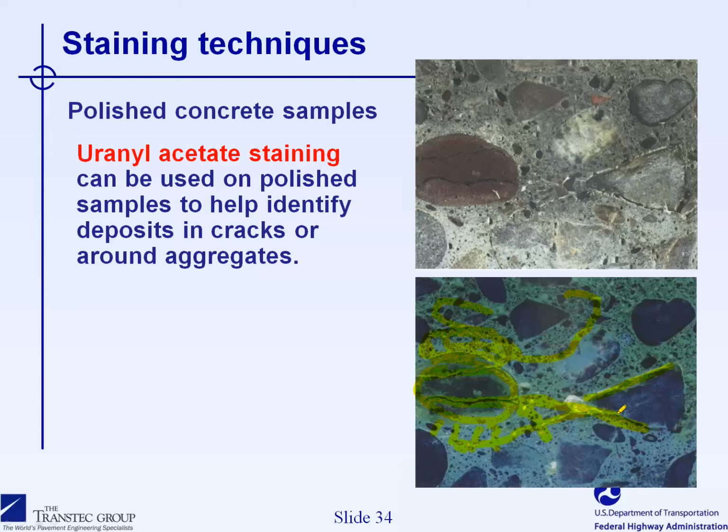Well, I would agree with Ben. We've seen cases where the damage comes from the coarse aggregate and from the fine aggregate. And not only that, we often see that the deterioration might come from just, say, a single size fraction within an aggregate. So I would say we've seen a whole range, from the relatively small particles reacting all the way to the large coarse aggregates, and any of them can be damaging to the concrete.